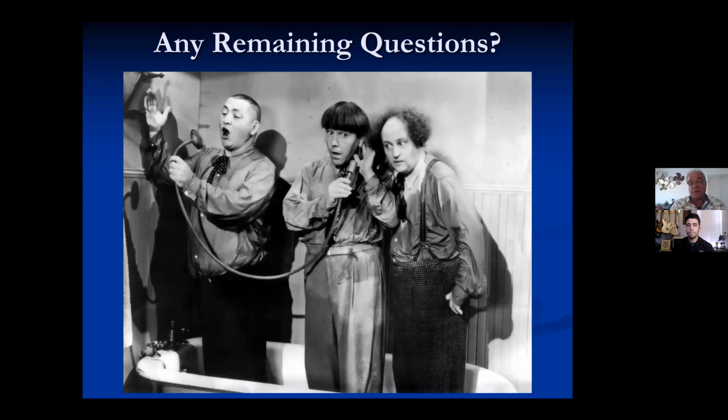And there's also some pitfalls. RF over fiber is great for wireless mic receives. But when it comes to in-ear monitor transmitters or wireless intercom, you can't put any power into it. You can't put more than one signal. So ask any of the people that do in-ear monitors on this webinar how often they only have to use one in-ear. The answer is probably, I wish, not anymore. There's usually 16 in-ears, and you can't do that with RF over fiber. So there are pitfalls to it. If you're going to use it, use it when it's appropriate and know its limitations.